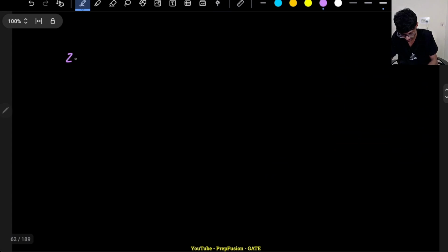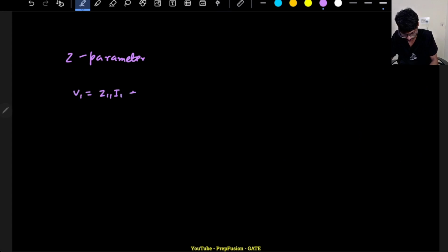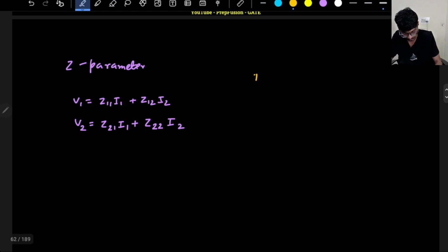So previously, in Z parameter, if you remember, what was the equation? I told you that in Z parameter, my V1 was equals to Z11 I1 plus Z12 I2 and V2 is equals to Z21 I1 plus Z22 I2. So of course, I told you at that point of time that I1 and I2 should not be a function of each other, right? So basically what I meant by that is I1 and I2 should be independent variables. They cannot be dependent with each other.